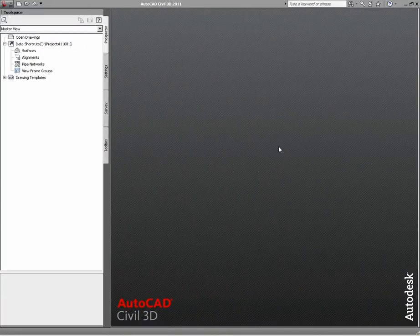The purpose of this video is to provide a brief demonstration on one of the easier ways in which one can take a drawing developed in Land Development Desktop with land development points and bring that drawing into Civil 3D for the purpose of converting the land desktop points into Civil 3D points.